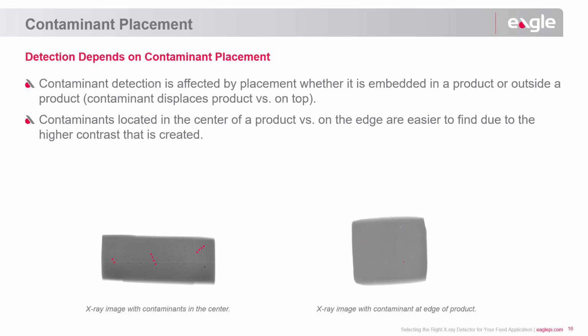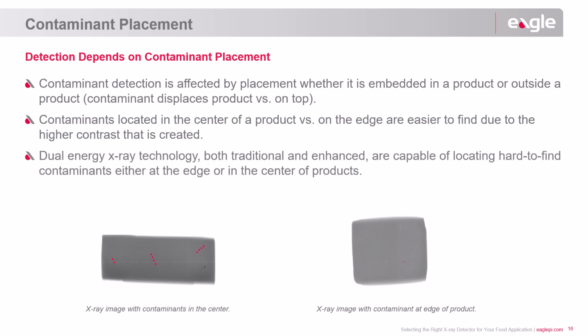When inspecting X-ray results, it's essential to position potential contaminants in various worst-case scenarios throughout the package. This approach ensures that your detection system is reliable and capable of rejecting any contaminated products during production, regardless of where the contaminant is situated.